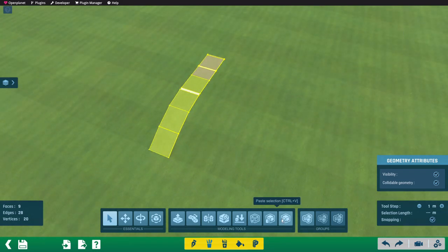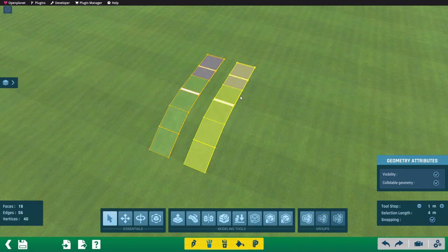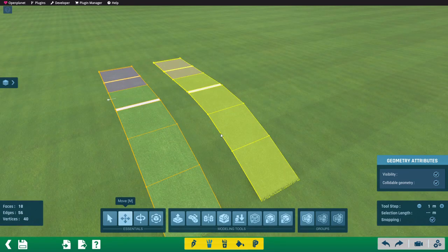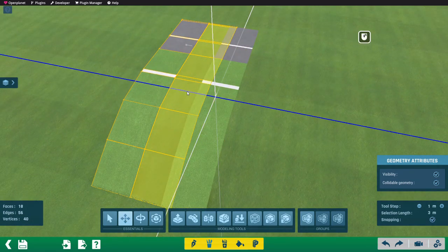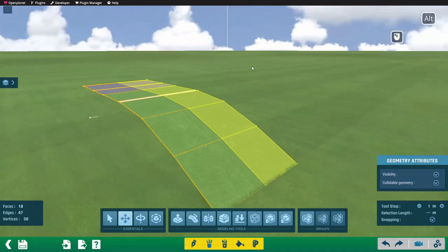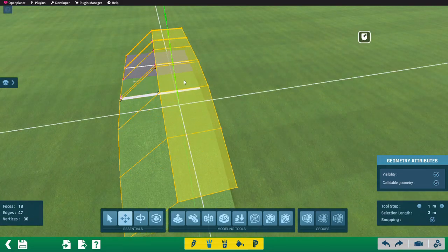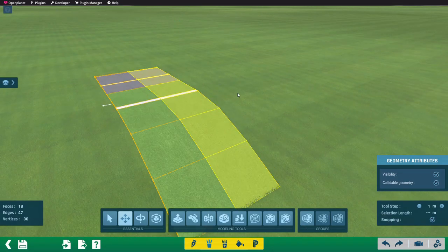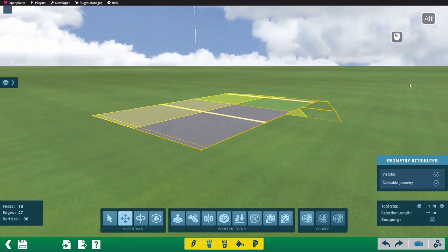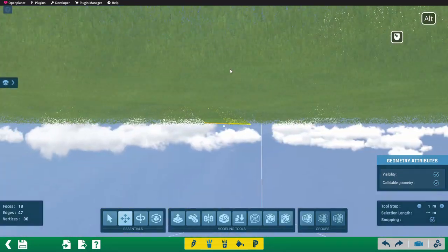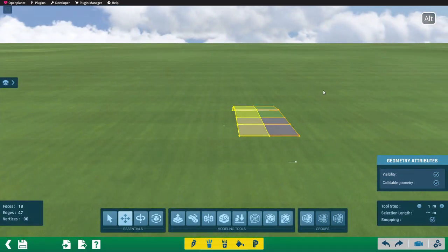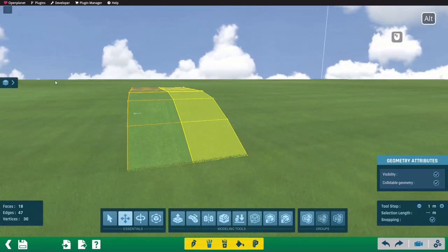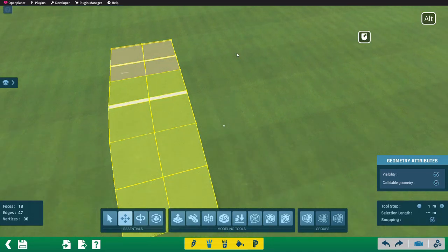To connect the two geometries, it's important not to paste the copied geometry directly onto the correct location. Doing so won't establish a connection between the geometries. Instead, they only connect when vertices are moved onto the same position. Working within a single geometry helps minimize shadow bugs and allows for easy variations to be made. I repeat this process several times, allowing the item to extend to the desired length, in this case 32 meters.